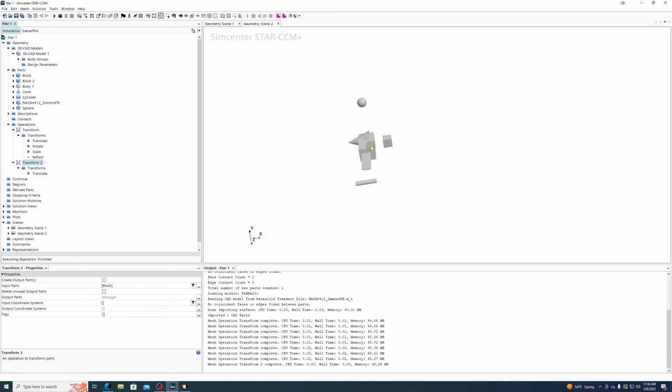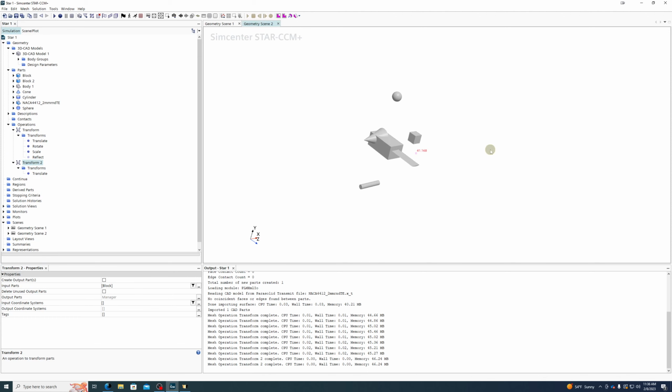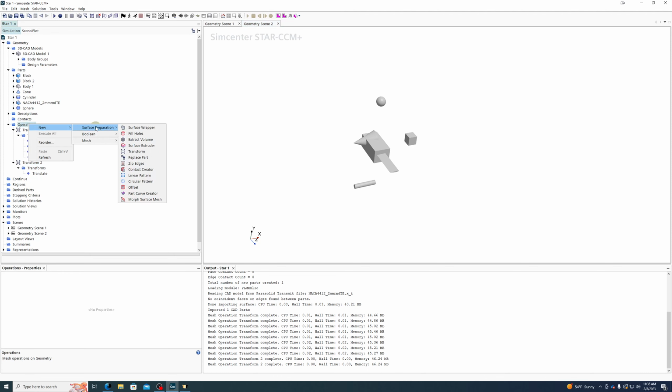And just move that block 2 meters in the X direction. 4 0 0. Execute. So you can do things that are mostly just limited by your creativity and how many steps you want to do. You can do a lot with transforms and basic shapes.